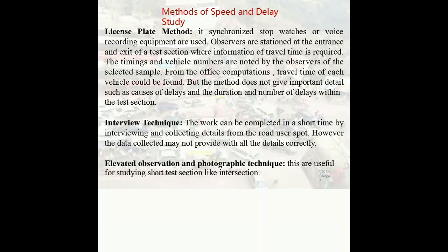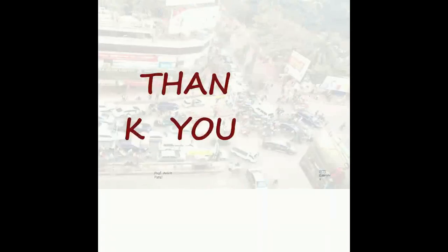In the interview technique method, the work can be completed in a short time by interviewing and collecting details from road users on the spot. However, the data collected may not provide all the details correctly. Then the elevated observation and photographic technique is useful for studying short sections like intersections.